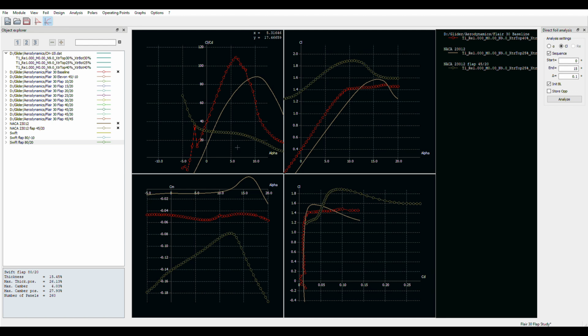In fact, intuition is opposite here. I need a bigger flap to really slow up? No, you need a long, skinny one at the trailing edge. That's what you need. So, big mistake. Might have put that hinge line there just out of intuition and thought, oh, handy for transportation too. Who knows? But it was just a wrong decision. And let me show you why it was really, really wrong and turned deadly.